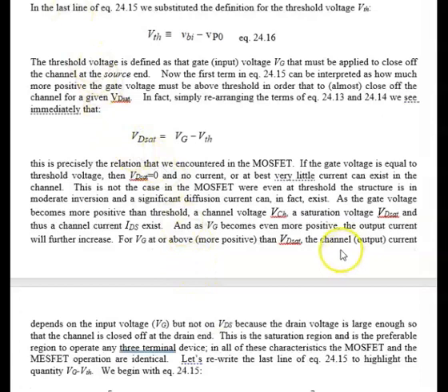But at least above V threshold, if VG is above V threshold, then the performance or the equations are reasonably similar. For gate voltage above threshold, we have a channel voltage, we have a finite positive VD-SAT, and we have an IDS, certainly.